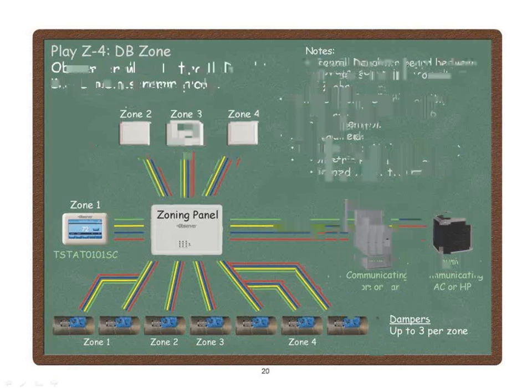Like I mentioned, the dampers really only require 3 wires. And like I mentioned, the condensing unit outside, if it's a 2-stage condensing unit and it's communicating, it only requires 2 wires. But if we just tell you to run 4 wires to every single thing, dampers, stats, zone panels, furnaces, condensing units, you're totally covered. Or run the 5-wire thermostat wire like we mentioned earlier, and you're super covered. You got a spare wire for everything.